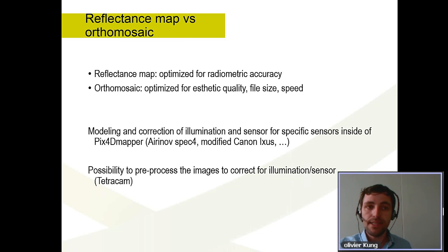Pix4D Mapper is indeed, as previously said, able and will model and correct the illumination and the sensor. It's going to do that for as many cameras as possible, but we are working very closely with camera manufacturers to have for certain cameras a very easy workflow to make it work as nicely as possible. Also, something to remember is that some of this processing can be done as a pre-processing step. For example, Tetracam is offering a tool to allow the correction of the sensor and of the illumination before processing them.